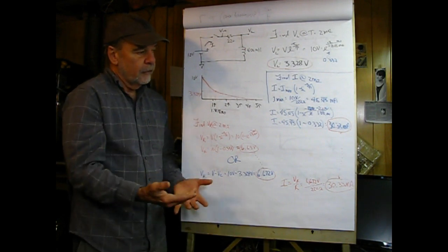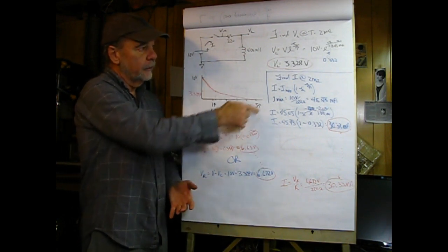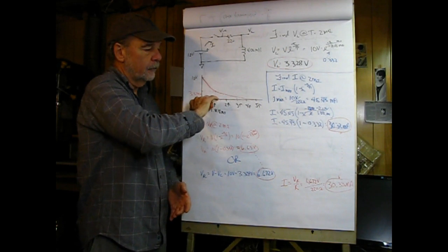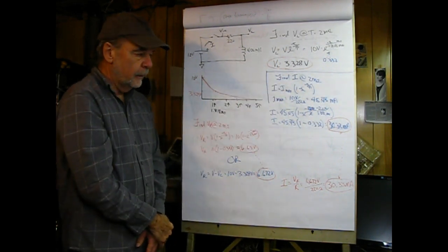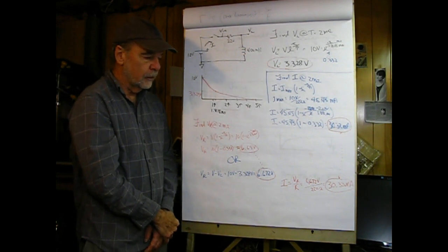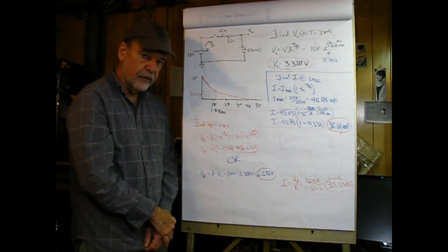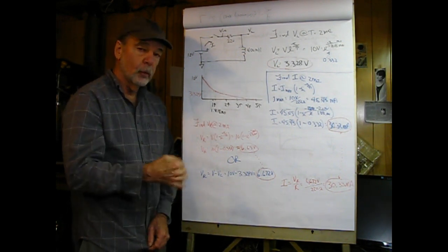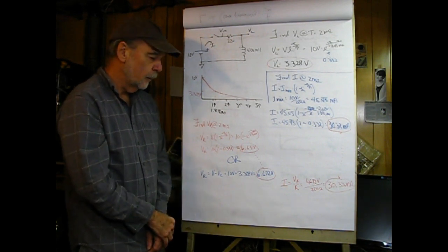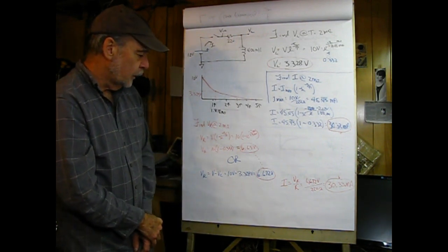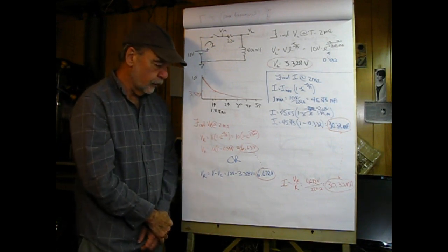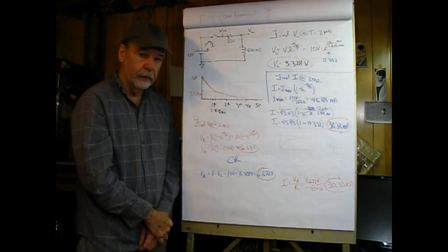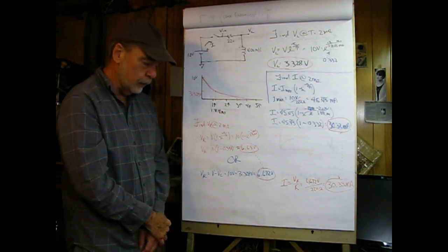When you look at these, if the curve is falling, you use this formula, and if the curve is rising, you use this formula. If we have any initial voltage across a capacitor or flux in an inductor, we would have to take that into account, but that's not our purpose here. So we can find VR, the voltage across the resistor at 2 milliseconds, and I've elected to do it verbosely here.